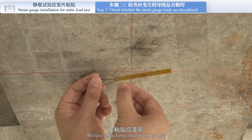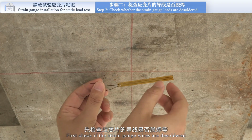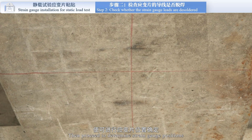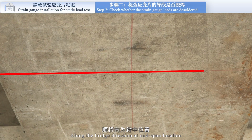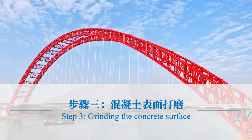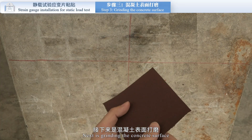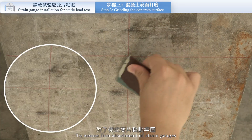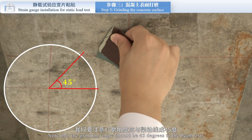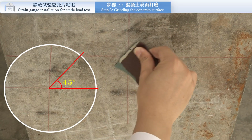Before attaching the strain gauge, first check if the strain gauge wires are desoldered. After completing the inspection, then proceed to determine strain gauge positions along the bridge direction at mid-span location. The transverse bridge direction is the central axis of the beam bottom. Next is grinding the concrete surface. To ensure firm attachment of strain gauges, note that the grinding angle should be 45 degrees to the beam axis.